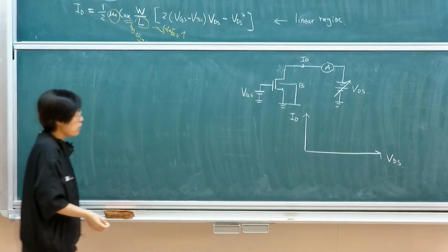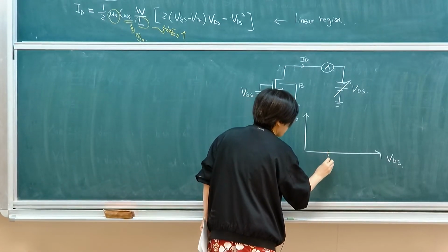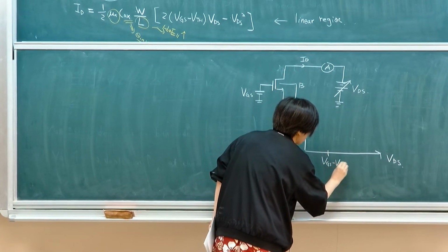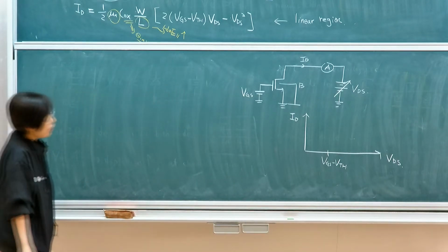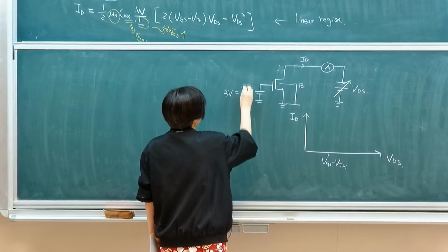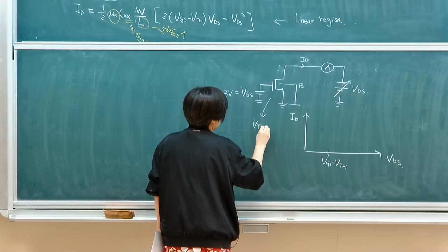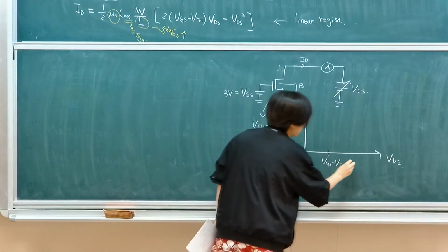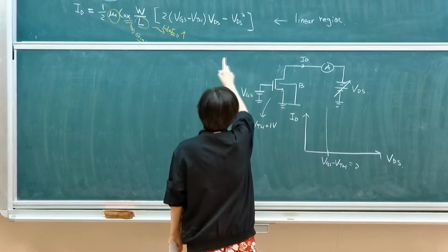We're operating at when? Let's say this is VGS minus VTH. Let's say this equals maybe 3 volts, and I'm assuming my transistor has a threshold of 1 volt. Then this will be 2. So before 2 volts, your characteristic will look something like that.